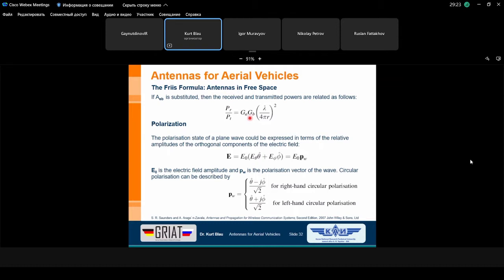It's logical: if the gain is very small, the path loss is higher, and if the gain is very high, the path loss is lower. Also given by the distance r, the radius of this imagined sphere around the antenna, and then you can determine very simply the path loss between these two transmit and receiving points.